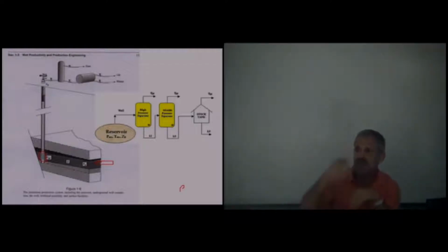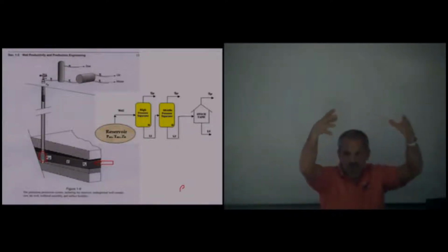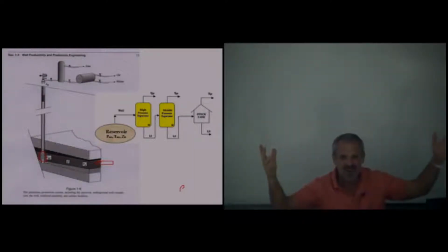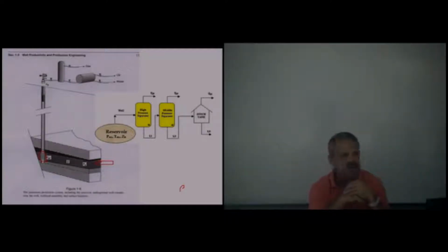And then when we get done, we take our pipe out of the hole and put our casing in the hole, and then we circulate cement down, and it circulates the mud up the annulus, and then we flush it with water, and now the cement's coming up the back side. So we've got cement between the hole and the casing, water inside the casing, and the mud out of the hole. Ideally, that's the way it all works. And then we shut it in and let the cement dry, and that's what we have in most situations.